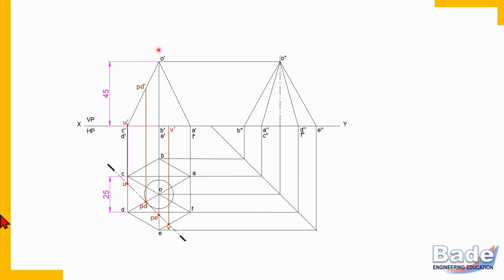But you don't get any sharp intersection on edge OE. This is what we discussed in the last problem also. If a point is on an edge that appears vertical in front view or in top view, then to transfer that point, we'll have to use a proper procedure. Try to understand the procedure, which is very much similar to the procedure we used in the last problem.